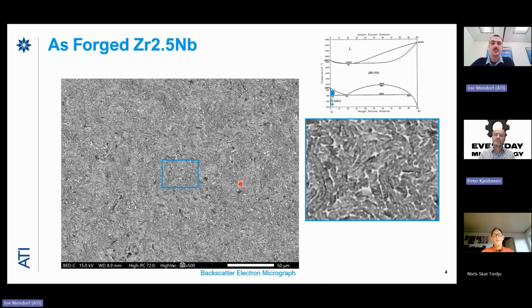Exactly. So how does it deformation harden? It's not just deformation hardening of these materials compared to steels, for instance. Is that similar? This particular alloy is fairly ductile and has a lot of strain hardening. I would say it's much softer than your typical medium carbon steel, and has a significant degree of strain hardening as you go through all of that plastic strain up to your ductile limit.